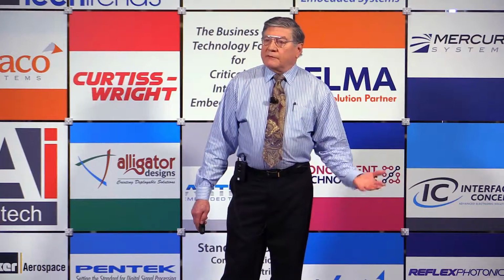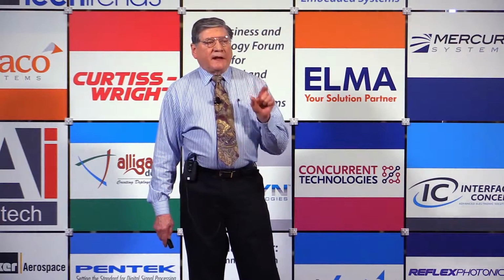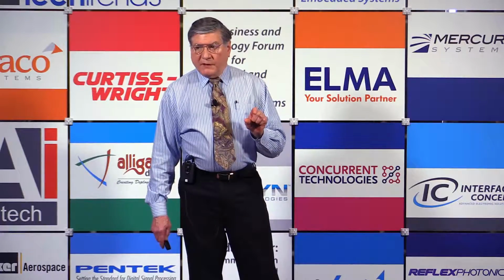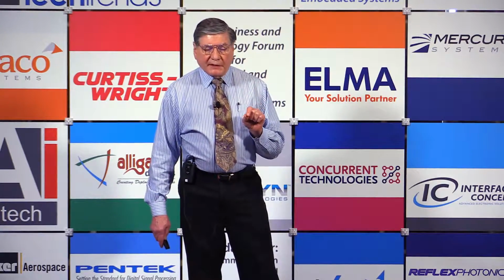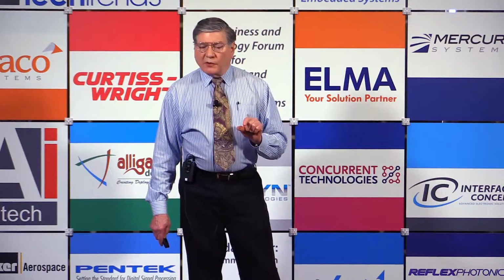So it's really, again, simple is good, and you change the clock rate to the A to D, the sample clock, the data rate changes. The FPGA takes it. It's very simple. The problem is, as we get faster and faster in data converters, as we get more channels, like multi-channel, dual-channel, quad-channel devices, the number of traces that you need on your printed circuit board really gets out of hand.